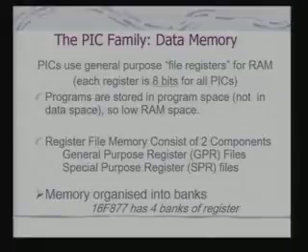Then we look at the PIC data memory. Now data memory is organized into 2 parts. One is called general purpose registers. The other part is special purpose registers, or special function registers.